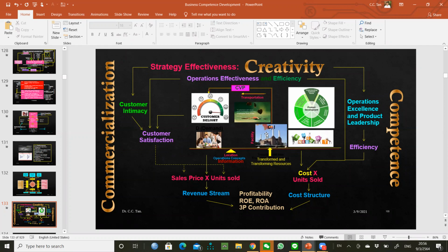And we have already talked a couple of times in other sections about how we can design the capacities, such as the requirements of the customer divided by the number of hours that your company is working in terms of shift. And from there, you can determine the speed of your production per day. And from there, you can do your machinery design and flexible manufacturing systems and things like that, and that is how you can quickly automate your system.